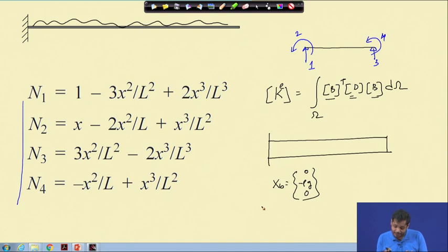Now, in addition to the body force, there is another force which is called surface force. For instance, if this beam has a load like this, uniformly distributed or varying load, it is acting on the surface. When I say surface, it is essentially acting on the boundary of this domain. So, this is called surface load. Similarly, the surface force is represented as S, and this is also a vector. It gives you the surface force, or traction, in which direction.